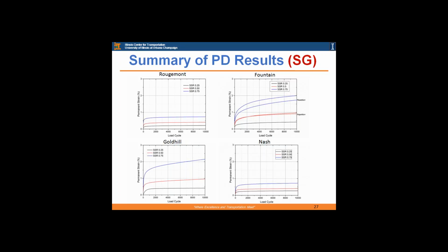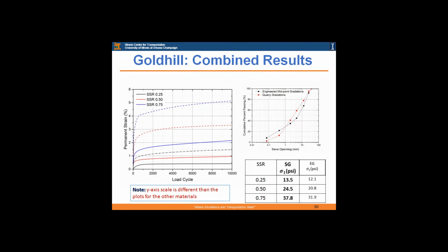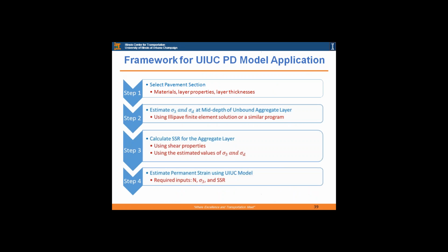You're basically bringing the stress state close to the static failure of the material. That's how, when you repeat the loading at that working stress level, it becomes more prone to rupturing, obviously at a higher rate. But then I think you did a good job answering your question.